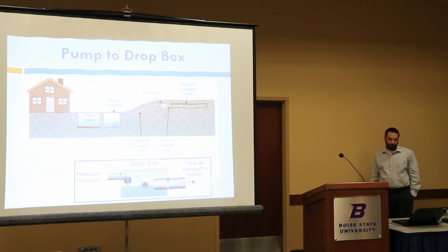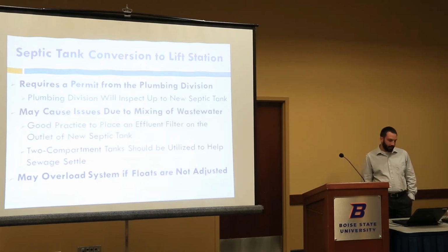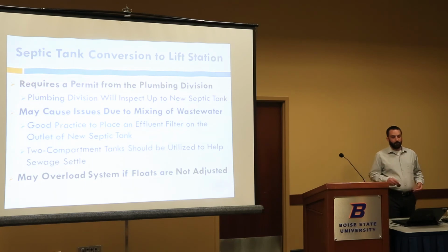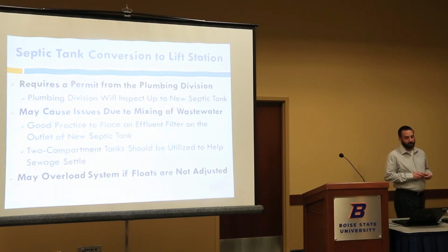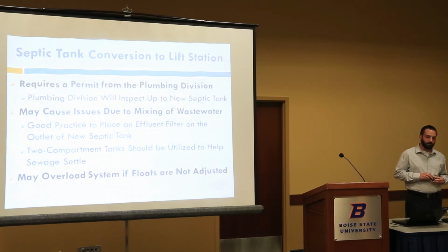That's what a typical system looks like, pump to drop box. That's in section 420 of the TGM, so you can find it there. Really briefly wanted to touch on septic tank conversions to lift stations. This is something we run into. It's not an update we did to the manual, but it's something we're seeing a lot of through permit reviews.